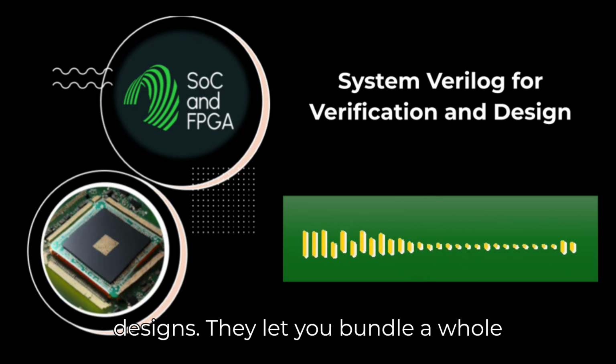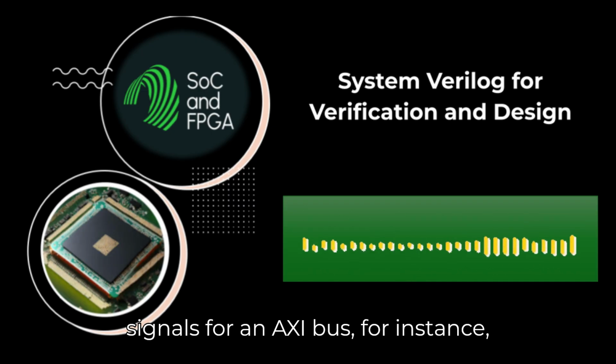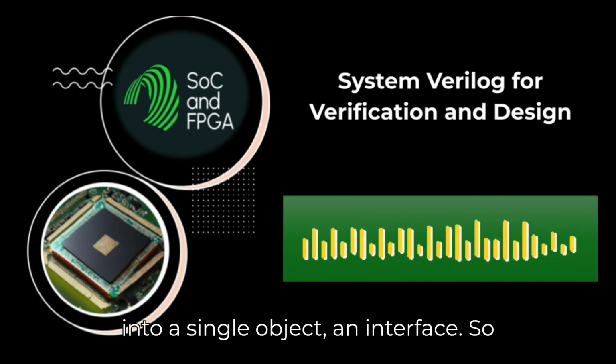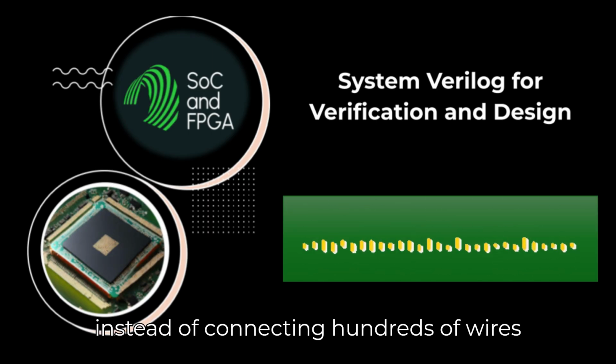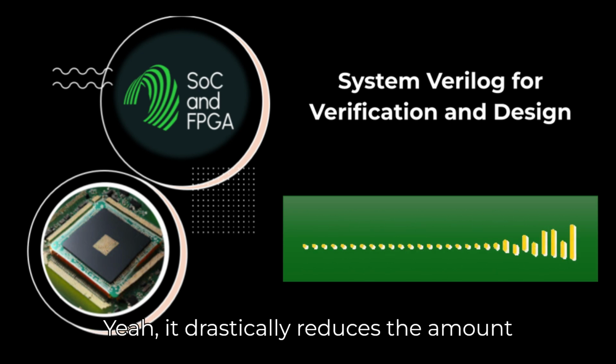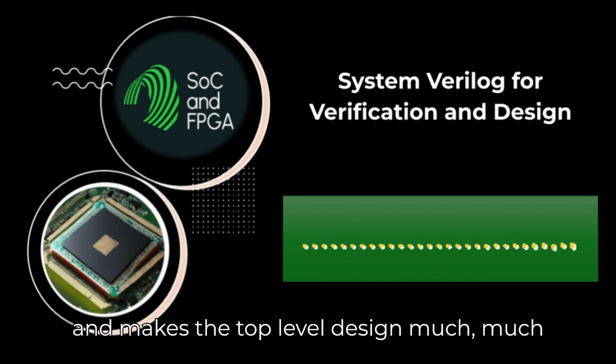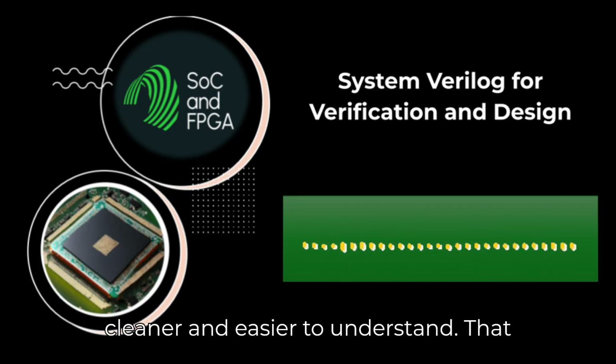They let you bundle a whole group of related signals, like all the signals for an AXI bus, for instance, into a single object, an interface. So instead of connecting hundreds of wires individually, you just connect the single interface instance between your modules. Yeah. It drastically reduces the amount of code, cuts down on connection errors, and makes the top-level design much, much cleaner and easier to understand.